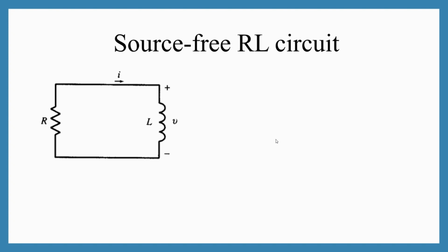We are going to assume that this inductor was initially connected to a voltage source through a resistor, of course, because in one of the videos I showed you how after there is a steady current flowing through the inductor, it acts like a short circuit, and therefore that would tend to damage the source or the supply. So we have an inductor here connected in series with a resistor, and say this is 10 volts. Now this is going to charge.